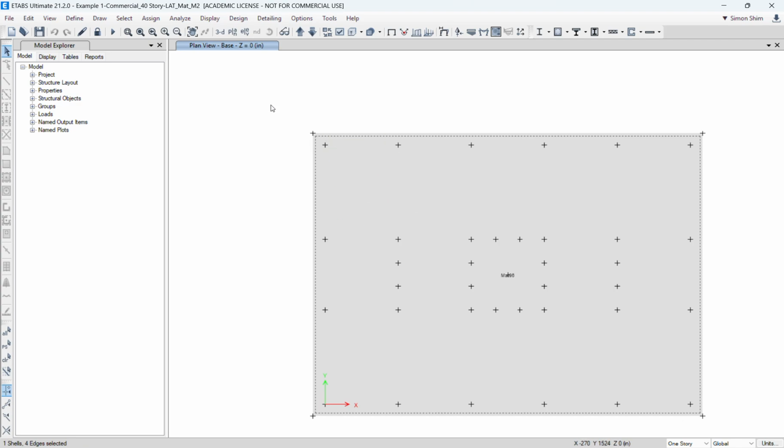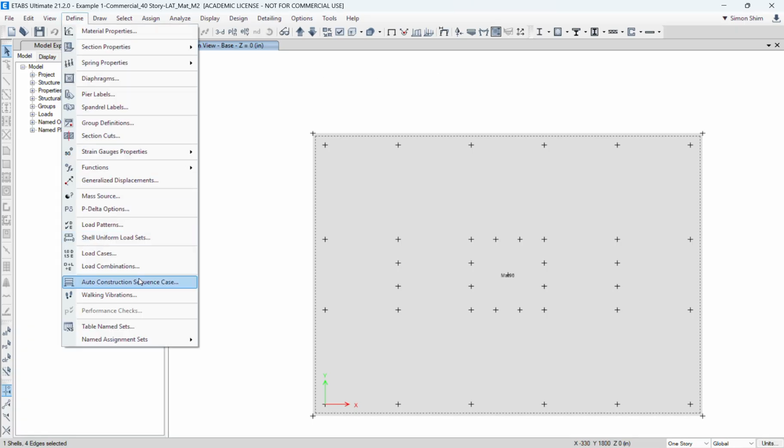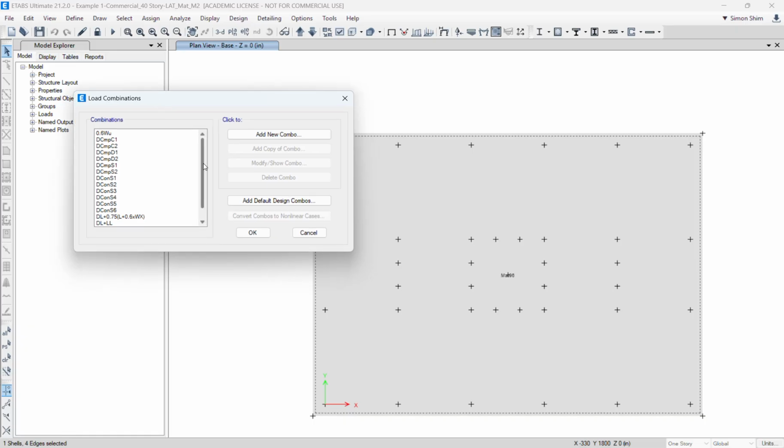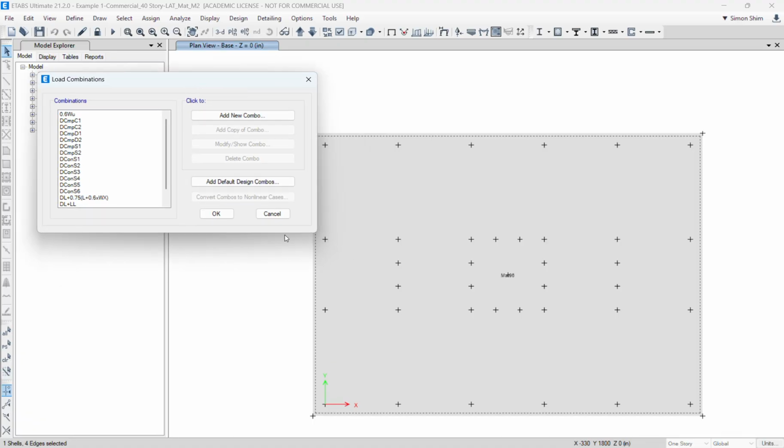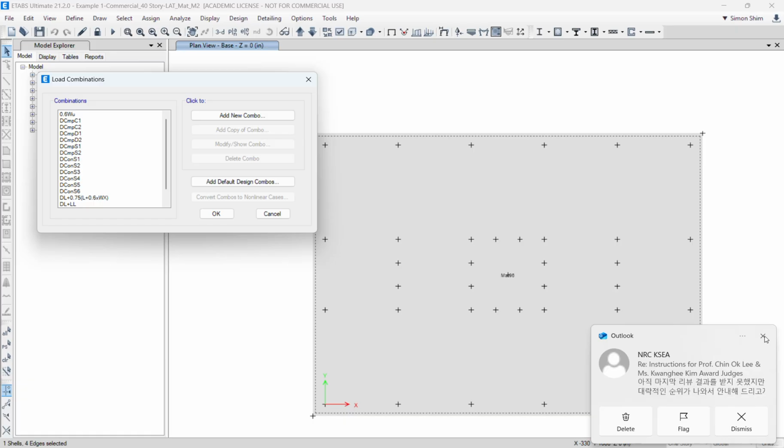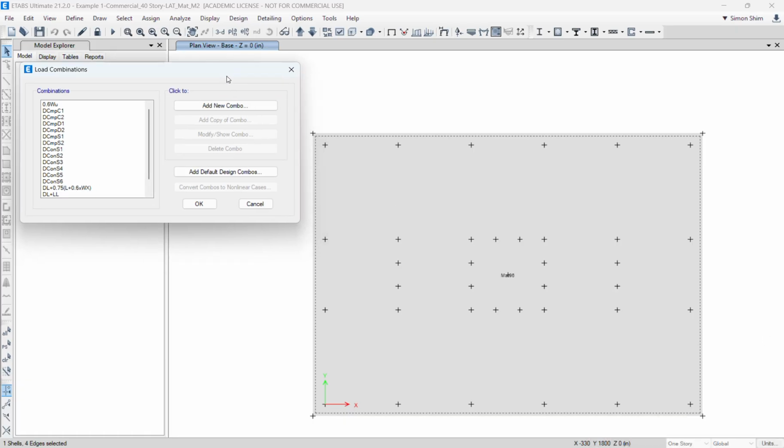So as you can see, the 3D model has all the gravity loads, superimposed dead load and live load, and the wind. First thing, I want you to remind yourself about the spread footing design. One thing we did, typically if you have dead plus live or service load, you calculate the required total area of the footing, right? So as to meet the soil bearing stress less than the allowable bearing capacity.